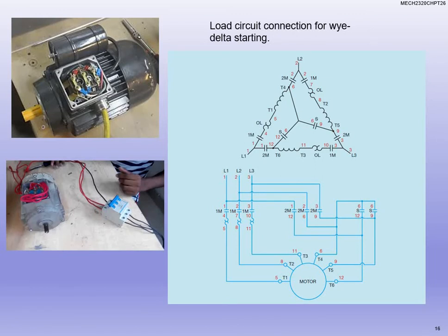So if we take a look at the motor, see where all those contactors are, T1, T2, T3, T4, T5, T6. Okay, that was on the diagram before. And so based on that, we know our delta to Y and how we hook those up. So some of that's going to be the delta, some of that's going to be the Y. And that's why it's very important for us to put all the wire numbers or the terminal numbers on all of these. Okay, so notice on the far right hand, those are our start versus our run. So very important that we understand.